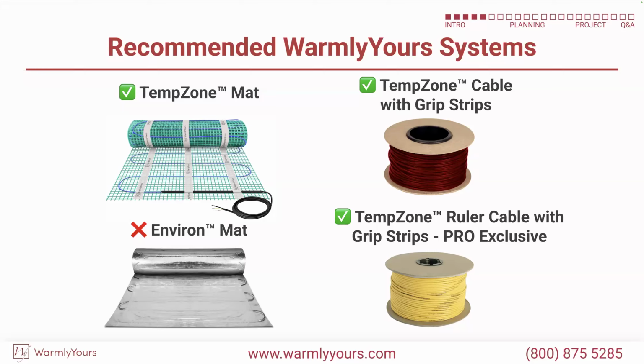Our other choices that we'd like to offer, for a little bit easier price point, would be our TempZone cable with grip strips or our new TempZone Ruler cable with grip strips. The difference between those really is the Ruler cable is set for our trade professionals who are in the industry, and it's just a little bit of a differentiator based on the style of the cable itself. But both are very good to use for under vinyl product. And all three of those, you're going to pour about a 1/2 inch of self-leveling cement over the top. And all of these things will want to float to the top of your self-leveling.